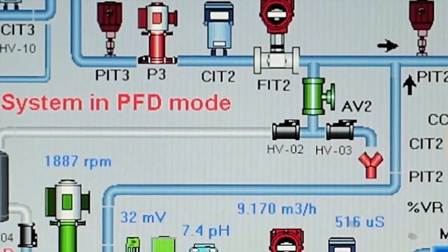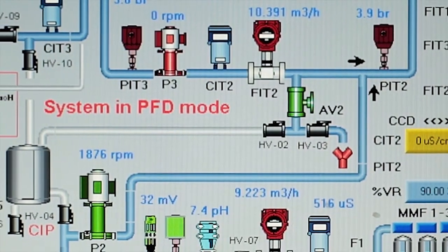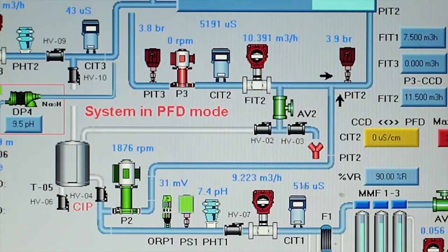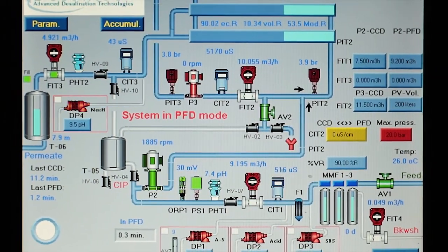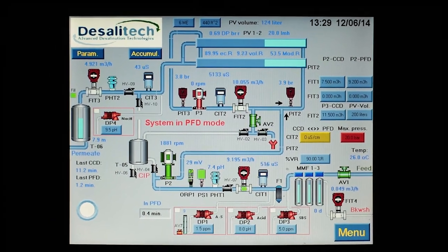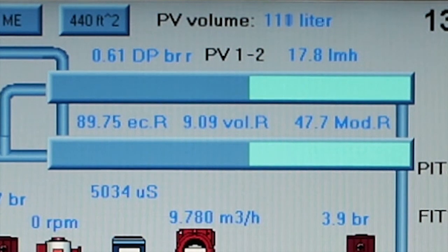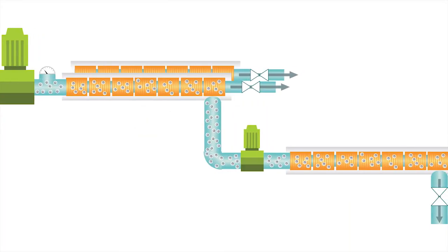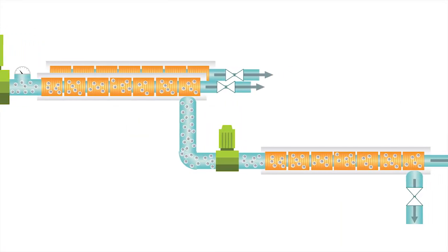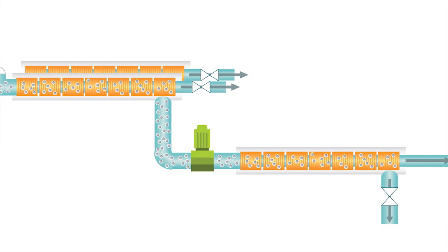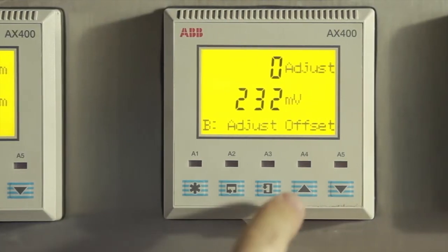whereas traditional RO systems typically operate at only 75% recovery. CCD systems also avoid scaling, which can ruin membranes in conventional RO systems at high recovery rates, by flushing the membranes frequently with fresh feed water. The short time during which the membranes are exposed to the high salinity does not allow scaling to build up. In conventional RO plants, recovery, cross-flow, and flux are interdependent, all supplied by the high-pressure pump. The CCD process decouples these basic variables, enabling their independent manipulation.